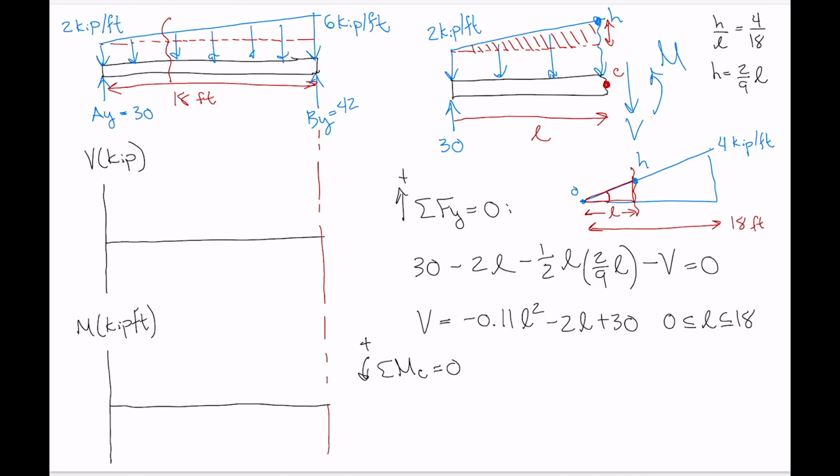That's a negative moment according to the system that I've set up for statics here. So we've got minus 30 multiplied by a distance of L away from point C. And then we've got positive, now the rectangular portion of that distributed load, its resultant is 2 by L. And its moment arm is L divided by 2. And then we've got the triangular portion of the distributed load.